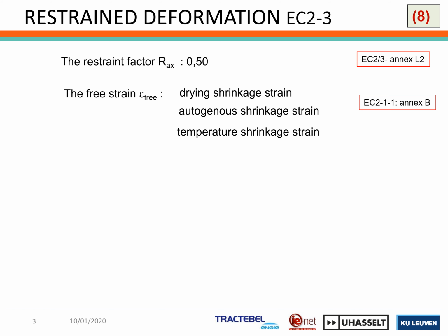This free strain is a sum of 3 types of strain. It's the drying shrinkage strain, the autogenous shrinkage strain, and the temperature shrinkage strain. But for the temperature, it's only the temperature shrinkage strain due to hydration of the concrete.